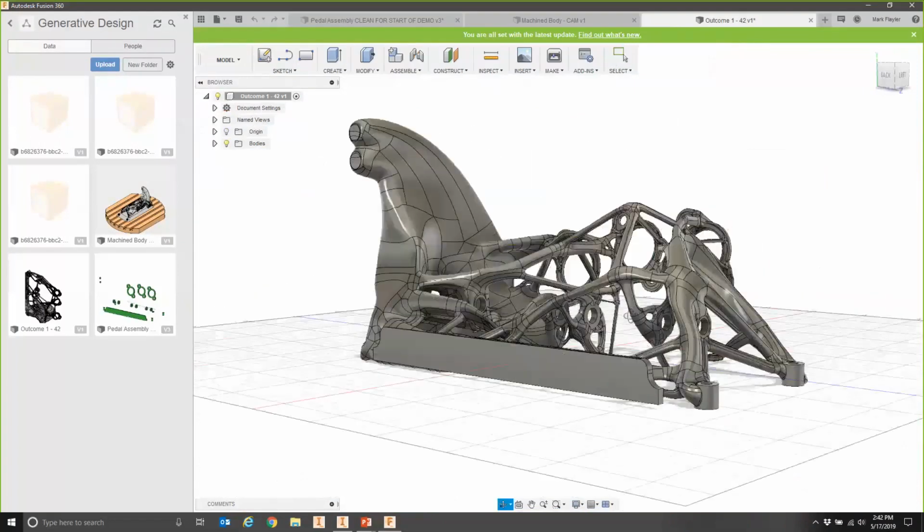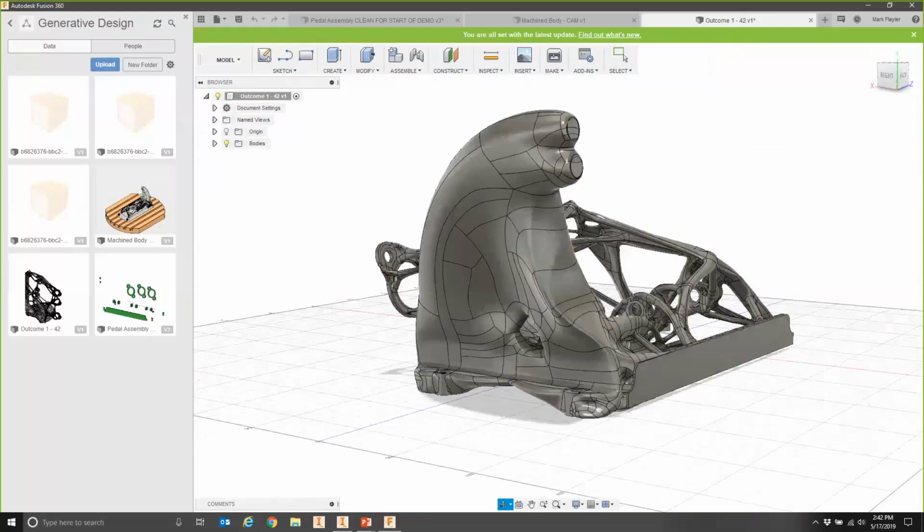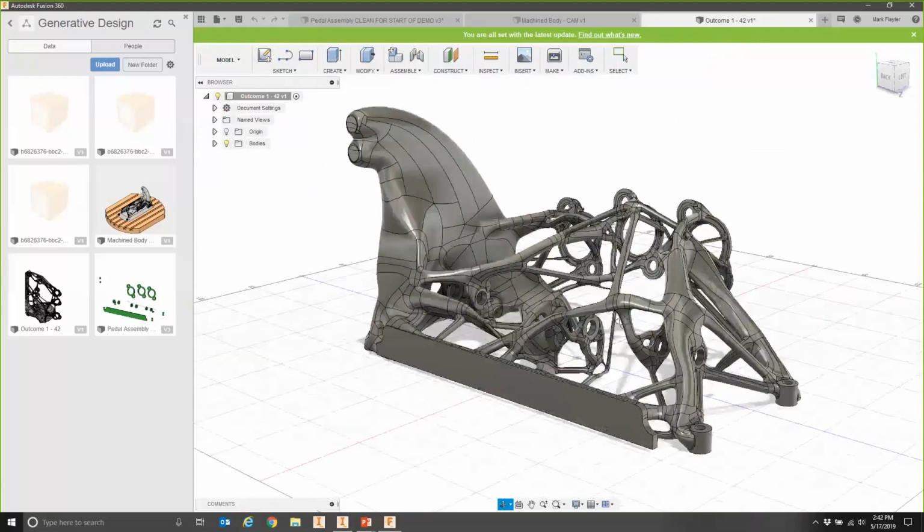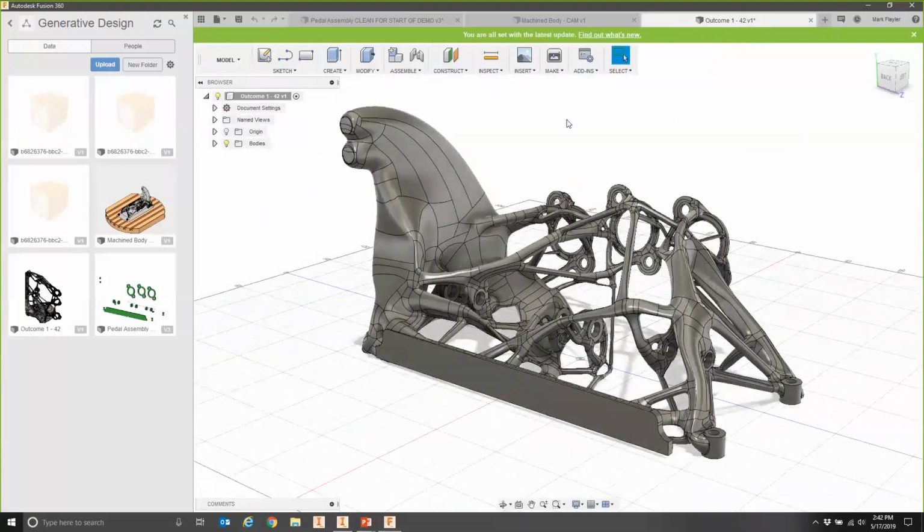So we would go from all those components down to just this one. Now, we all know that this doesn't look traditional. There may be an initial high cost of the additive printing, the additive manufacturing that's going to go behind this, and then the milling associated to it. But the ability to have a lighter weight part inside of something that's designed to be lightweight and also maintain stiffness and integrity can be a very important thing.